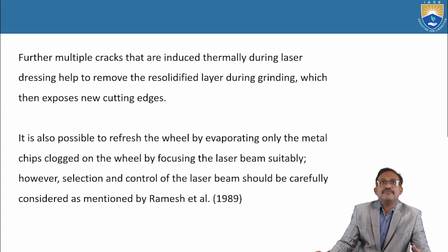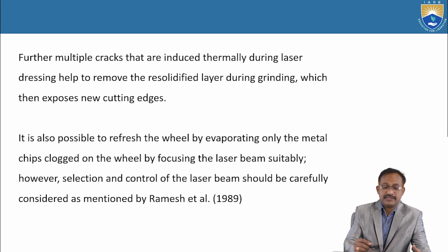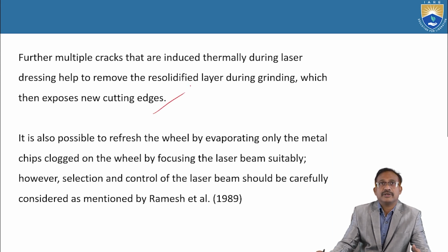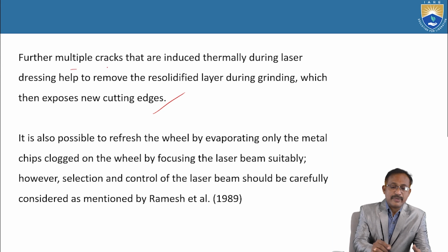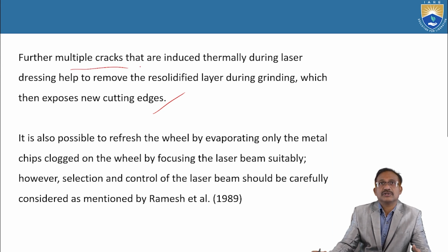Further, multiple cracks that are induced thermally during laser dressing help to remove the resolidified layer during grinding, which then exposes new cutting edges.